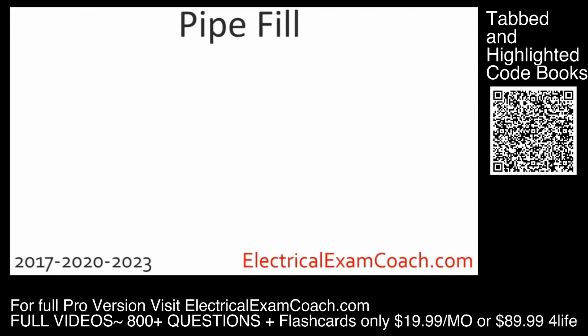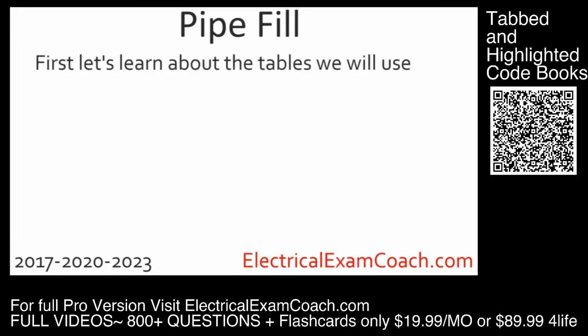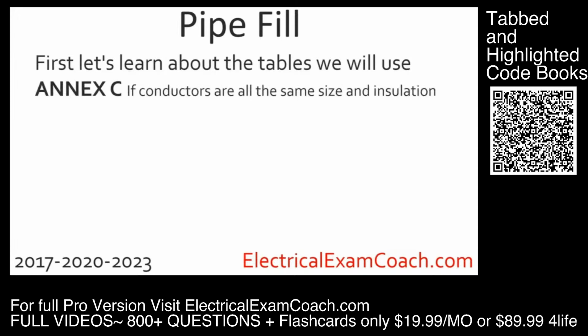The next lesson, lesson 7.2, will deal with if we have different sizes of conductors and different insulation types, meaning if I have 10s and 12s inside of the same conduit. Let's go ahead and learn about the table that we'll use if they are all of the same size. We're going to use Annex C. And if you've tabbed your code book, you have an Annex C tab. And if you haven't tabbed it, you can just follow along.